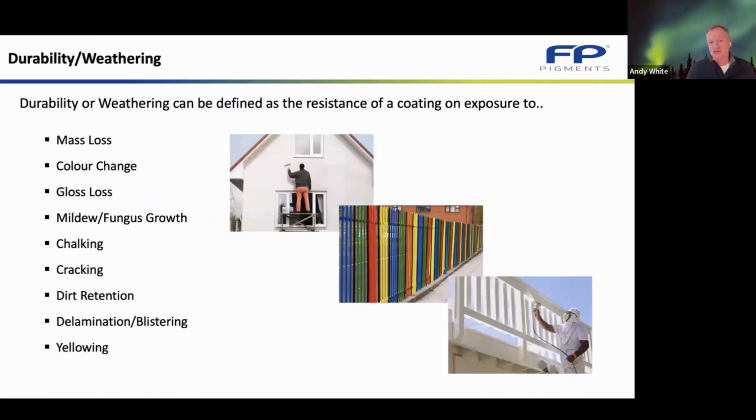And finally, durability and weathering. This is fundamental to titanium dioxide because in general, all of these problems that you can see from durability with this mass loss, color change, chalking, cracking, dirt retention, a lot of it is related actually to the titanium dioxide in the paint.